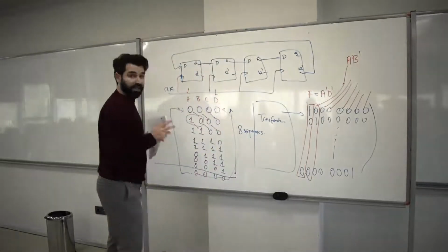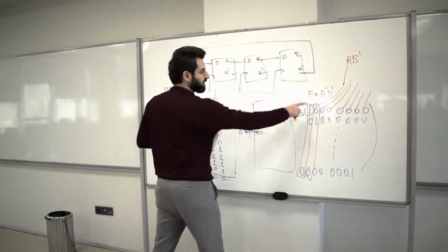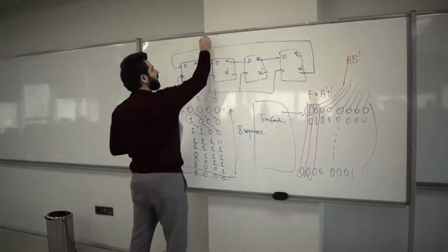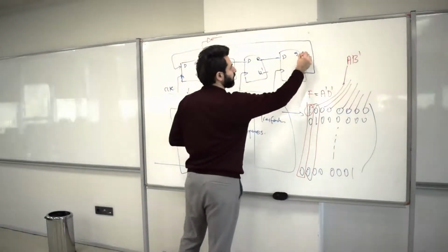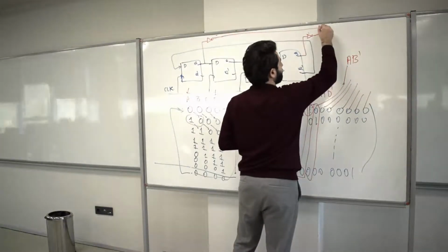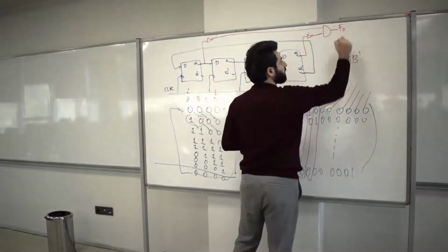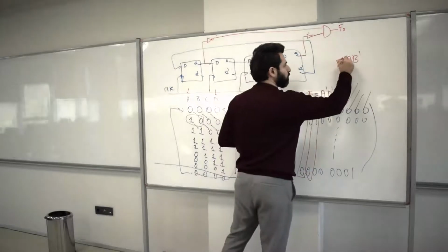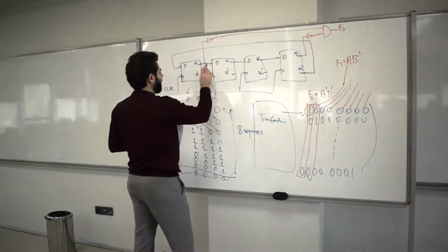Because now, what that means is that, for example, in order to generate this one, you connect a NOT gate to A. This is my A, by the way. So that's my NOT gate. And B, another NOT gate, which is this one. And then AND them together, to generate your first, this is F0. And similarly, for this one, let me just call it F1. That is A and B prime. So this is my A.